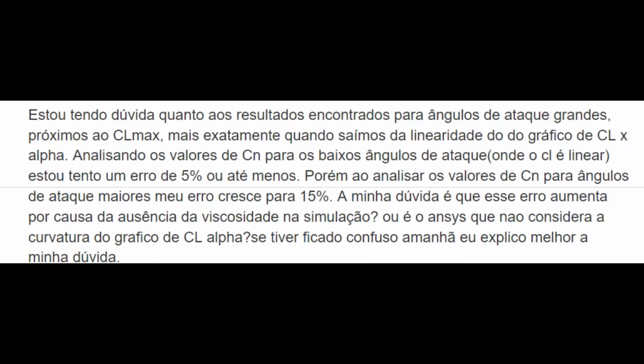High error is caused by two reasons. First is that you have no viscosity, so it's basically calculating with schematic viscosity, which is very different from the real viscosity. There is so-called approximation or numerical viscosity, and this is not inside the model. So there is no model of turbulence and there is no model of the boundary layer. So it's basically just flow without viscosity.